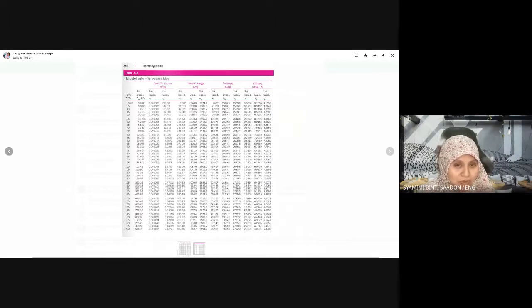Okay, thank you, Umi. Since we have the mass, 8 kilogram and 2 kilogram, we take the saturated liquid specific volume and multiply with the mass of the liquid, which is 8 kilogram, and the other one for vapor, 2 kilogram, since 10 minus 8 is 2 kilogram. So multiply both values, then add them, and we get the total volume of the tank.